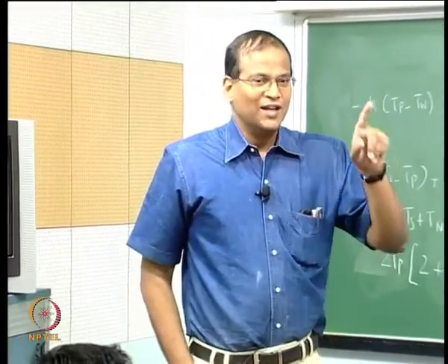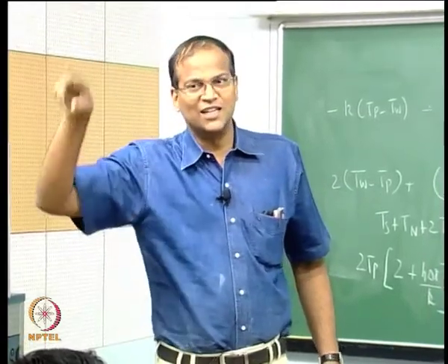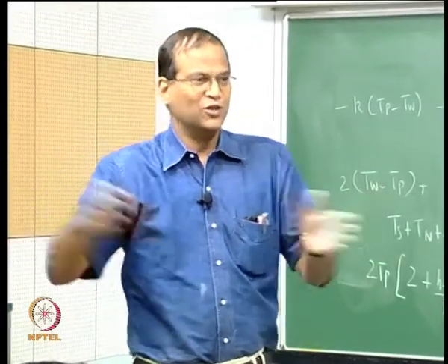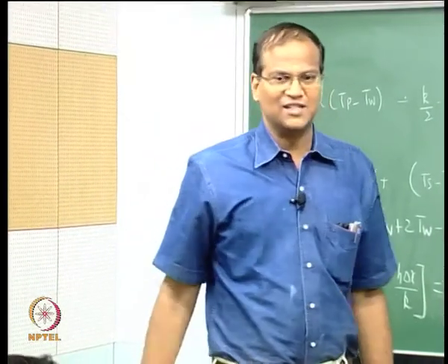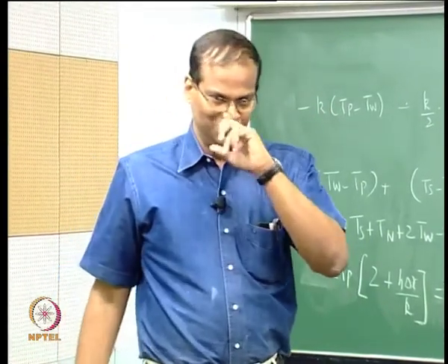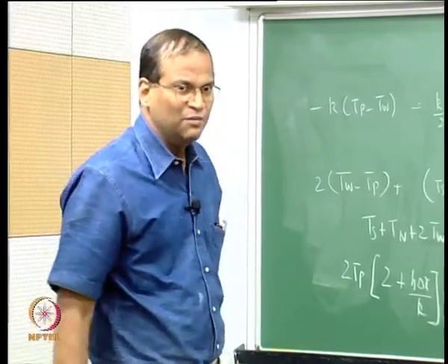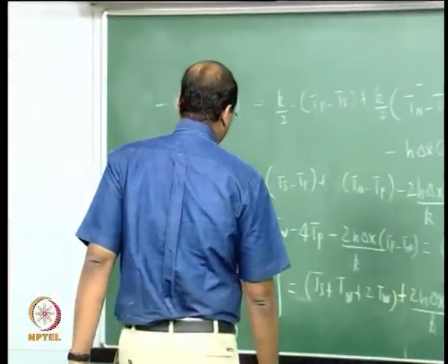So that is why, if it is adiabatic, you can just extend the domain and make it another half, so that you can use the east plus west plus north plus south by 4, which I told you yesterday in yesterday's class, method of superposition. That is the image point technique, that is what people call the image point technique.